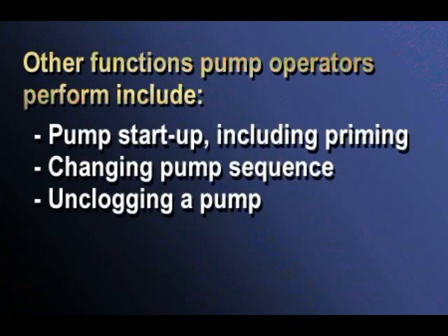Other regular operational functions relating to pumps that operators perform include pump startup, including priming, changing pump sequence, and unclogging the pump. There are also maintenance activities, which we will discuss later. These maintenance activities include maintaining proper lubrication, in addition to checking and replacing packing, mechanical seals, impellers, wear rings, and so on as required, checking the alignment and adjusting as required, and cleaning and repairing motors, couplings, bearings, and pumps.